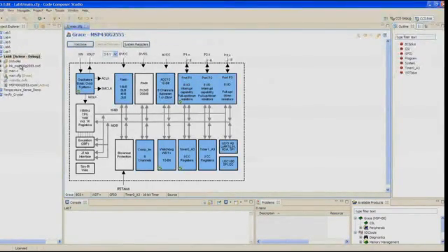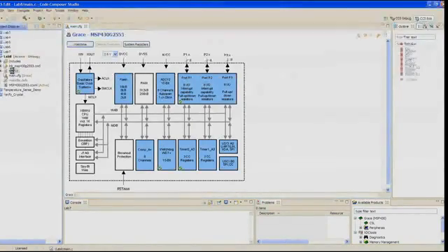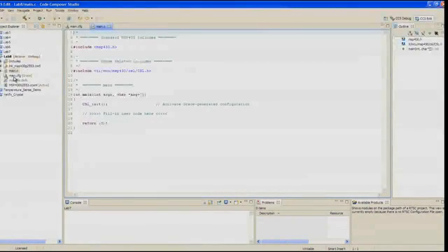Well, Grace automatically creates a main.c template for us with the appropriate Grace calls. Double-click on main.c in the Project Explorer pane to open the file for editing. So you should see the MSP430.h file in there. You should see some Grace-related includes like CSL.h, and then there's our main code right there. The standard MSP430.h definition file is included first, followed by the Grace definitions.